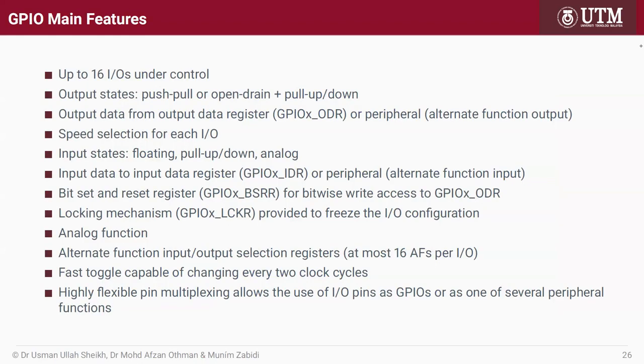All right, so these are the main features. Up to 16 IOs under one port, and the output can be push-pull or open drain, plus pull up or pull down. Push-pull and pull up is different. Push-pull is not the same as pull up or pull down, and then it has open drain.